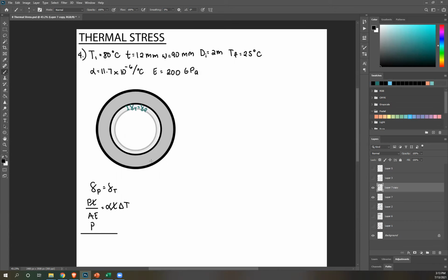okay. So now we need to get the area of our object. So remember, area is the cross-sectional area perpendicular to the direction of elongation, right? So usually, yes, we have a pipe, right? It's going to elongate, then this is our cross-sectional area. Now what about this tire? So if we try to cut our tire, okay, we'll have something like this.